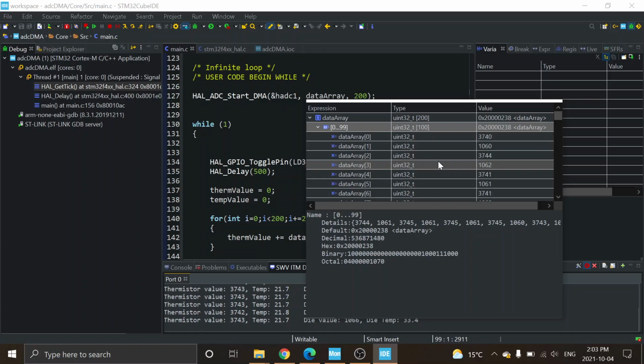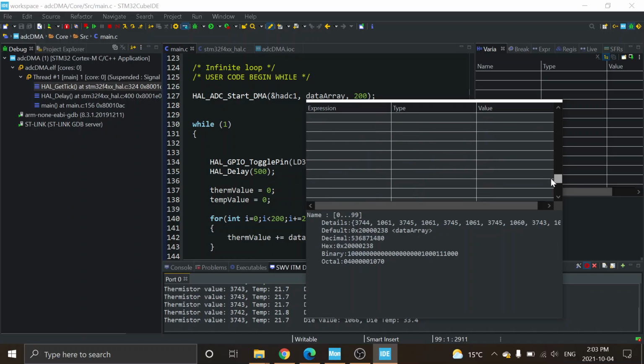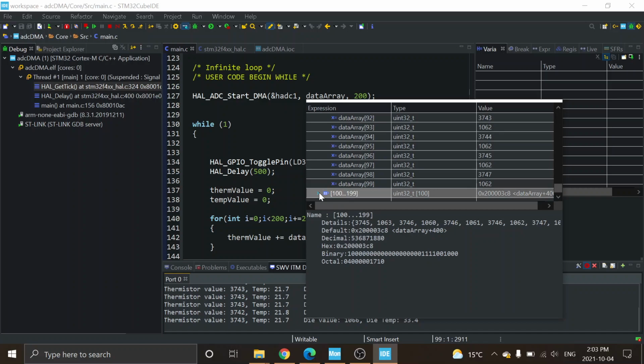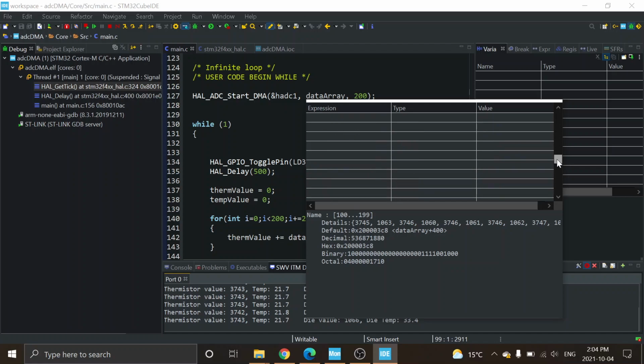And so some things that you can get, like for instance, here, I would know that if I had really, really big values, I've probably messed up word and 16-bit values and 32-bit values, okay, over here. And so we can scroll down through this, go all the way down, and they go, okay, that's good. And then I'm going to open up 100 to 199, if it'll let me. And then we've got all the values going from there, just alternating between. Okay, but that's a nice way of checking in and seeing if things are working.